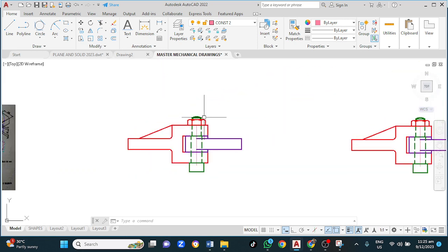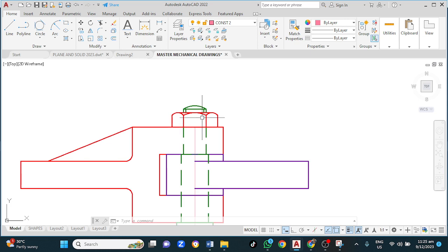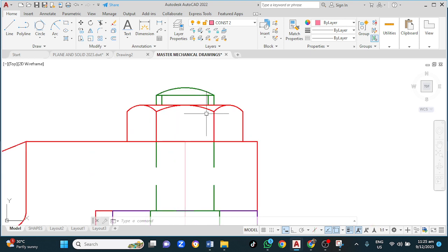So with those three rules, the fourth rule also states that we do not section nuts or bolts, but we do section shaft. Here I need to offset this to produce it, to generate the thickness for the thread.